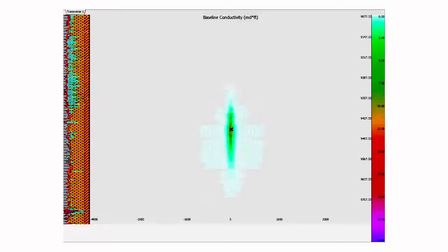Okay, pumping. Well, I think it's already done. Part of it's scaling. This is 0 to 25 millidarcy feet, so it's hard to see what the lower conductivity ranges are as far away from the wellbore. But you can see that as the sand is falling, so is the conductivity. And we're getting ourselves, by the end of this video, 12 hours after the pump stop, of what we would think is the best, most conductive region for this well, assuming that our inputs are good.